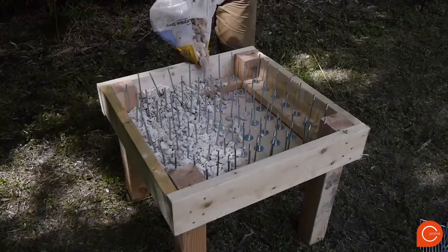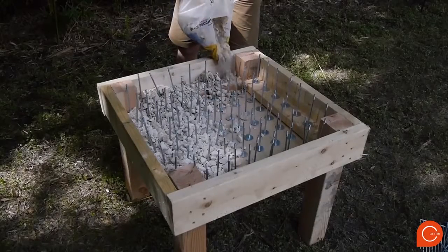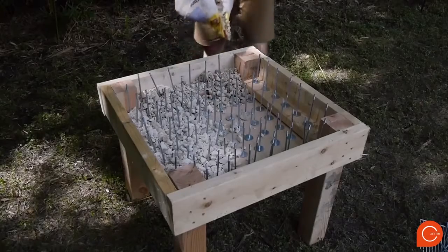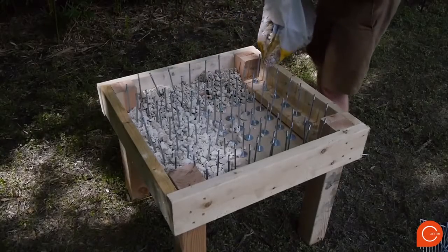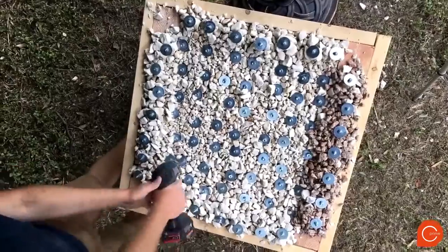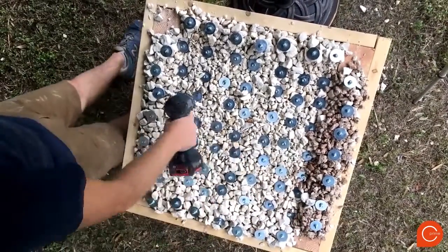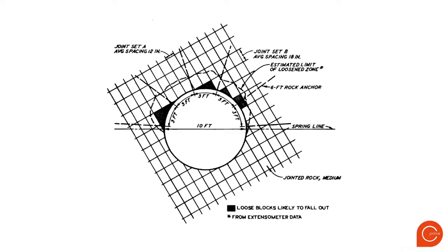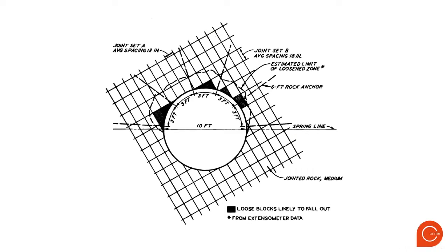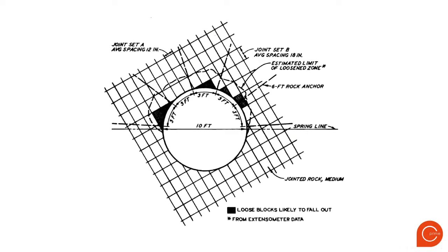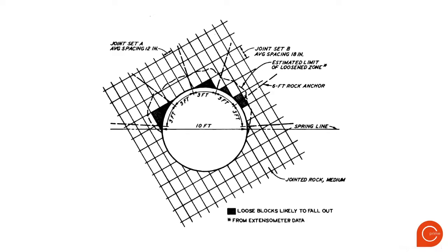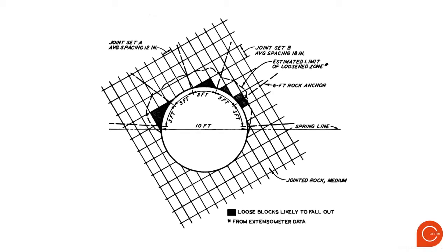The other difference is the scale. Although there isn't a fine line between soil and rock mechanics, gravel really falls into the soil side. It would never be feasible to use this many rock bolts just to stabilize a gravel mass. You would just line the tunnel. Rock bolts are most feasible when you're tunneling through jointed rock, where you can put a little more space between the bolts. But this demo is just to show that it can be done.